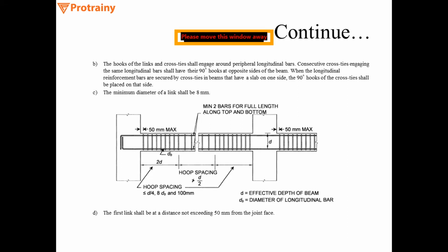Looking at the diagram, as you can see, there are several locations where the spacing changes. Talking about the mid zone, spacing should be not greater than d by 2, where d is the depth of the member. So either as per the design standard or d by 2.